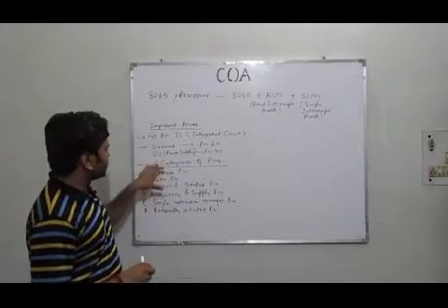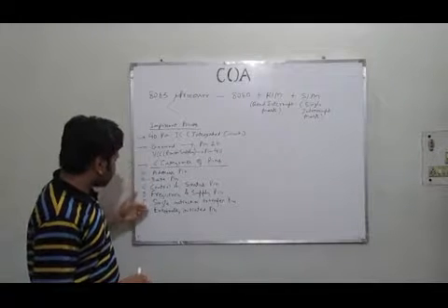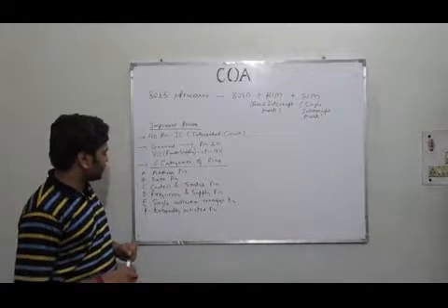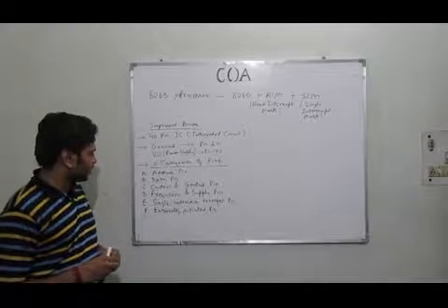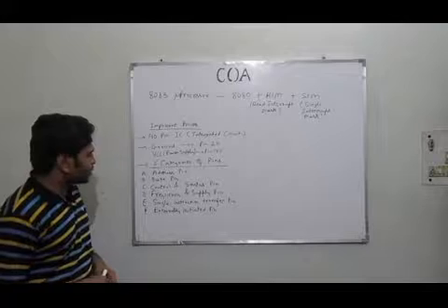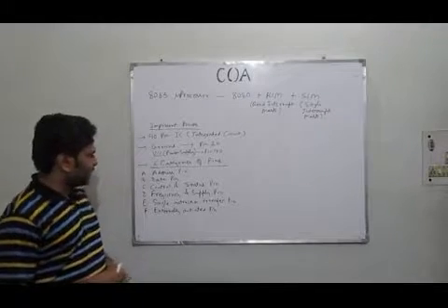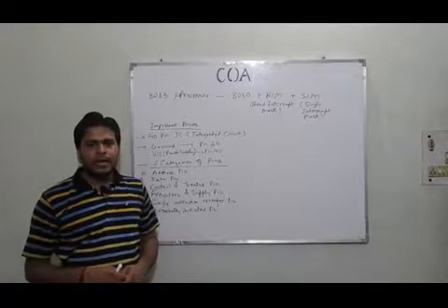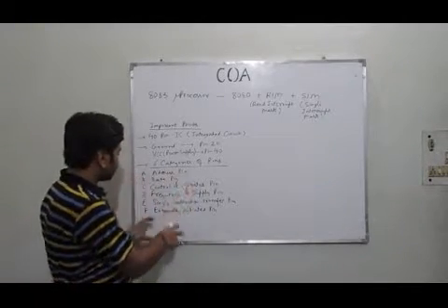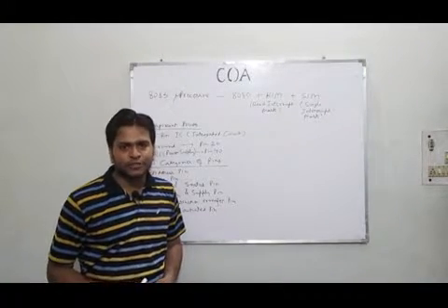We can categorize these 40 pins into six kinds: address pin, data pin, control and status pin, frequency and supply pin, single instruction transfer pin, and externally initiated pin. Let us check how these six kinds of pins are placed on the architecture of the microprocessor.